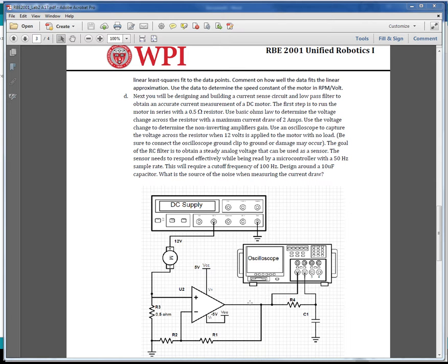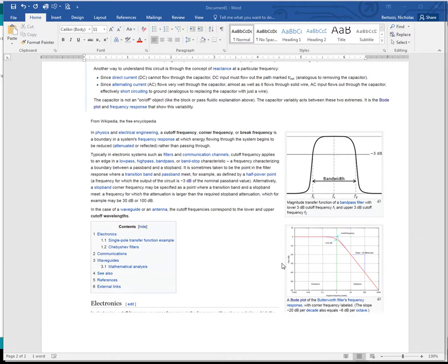And then what happens if you add in some high frequency noise here? As that voltage spikes up, you'll see the spike here. But what happens, of course, is the capacitor, you can't have a sudden change in voltage, right? You'll start having some current flowing into it, and the voltage will gradually come up, and then if the voltage drops down, it will gradually discharge. So the idea is that this smooths out the noise and takes out the noise. So this is a good way to reduce the noise, but it's not perfect.